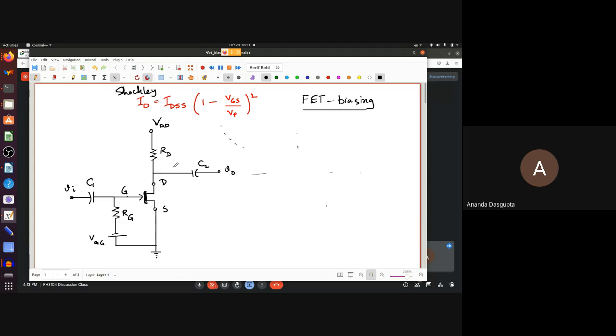You have just two resistances, two batteries, and one JFET. That's it. And by the way, we know that it's an N-channel JFET from the symbol, because remember this arrow that we put on this gate. This arrow essentially shows that this is like the diode arrow. It says this side is P, this side is N. So it says gate is P, the channel is N.